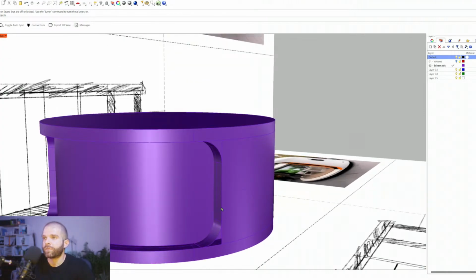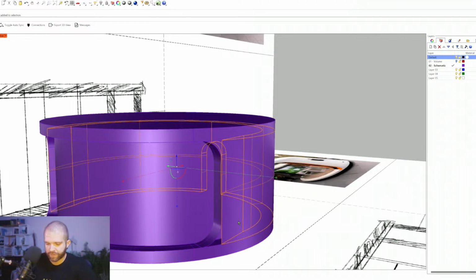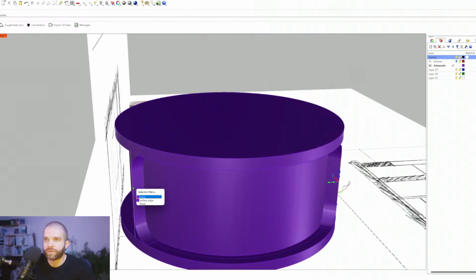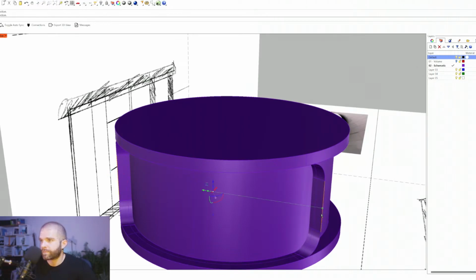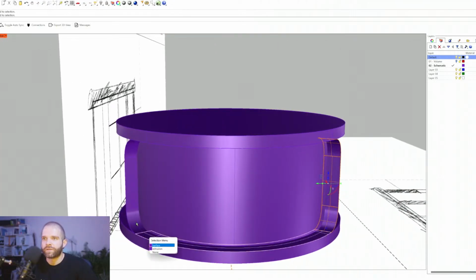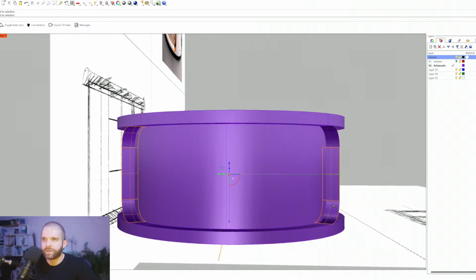And we basically just want to peel this edge back. So I'll hide this rather. I'm going to peel this face back, so I'm going to grab this edge and this edge. There we go. Control Shift click just to select those edges. And I'm just going to move them on the x-axis. Oh, I guess they got separated from everything else. I'm going to make sure that I join them together. Join. There we go. Now it's all one.